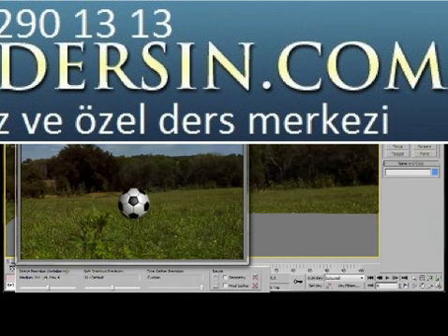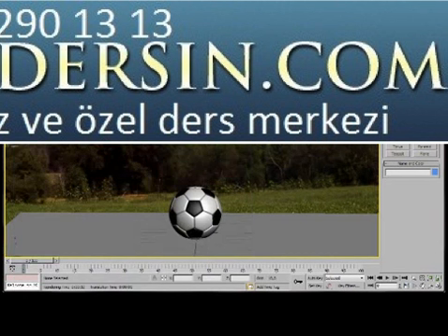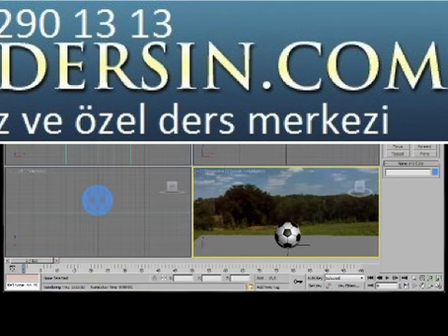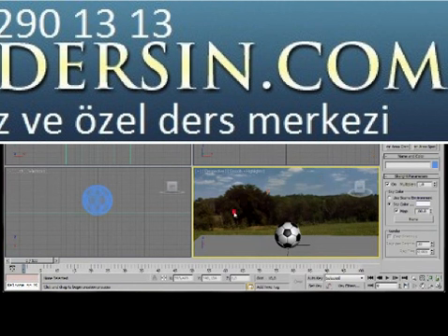Thanks to the special effect of the matte shadow map, it looks as if the football is in the scene. But if we add a couple of lights to create some shadow, the scene will look more realistic. Let's add some lights. Go down here to the bottom of the screen, click on Maximum Viewport Toggle and toggle back to the 4 viewports. Then we'll go over and select our lights. Behind the photometric lights, select Standard. Then we're going to click on the skylight and drag a skylight into our scene.